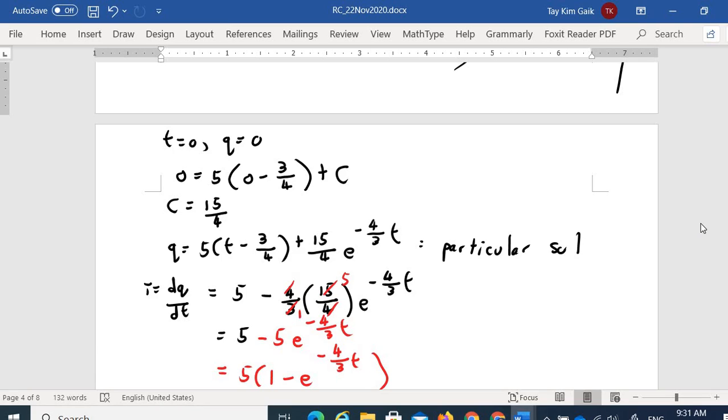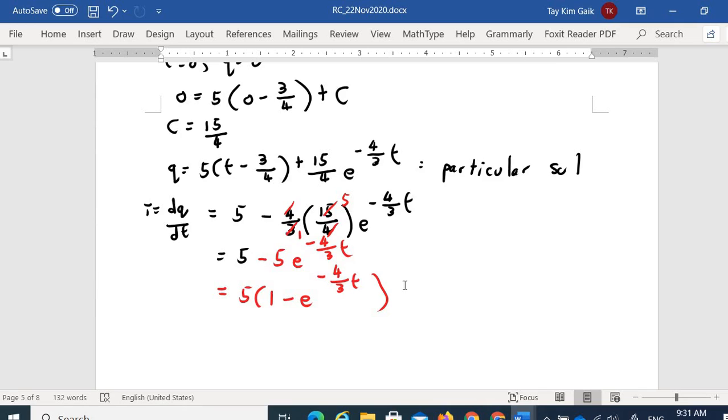As I know dq dt equals I, I differentiate it and I will get I. I check this with example 1, where I modeled the RC circuit directly in terms of I, and it tallies. So my Q is correct.